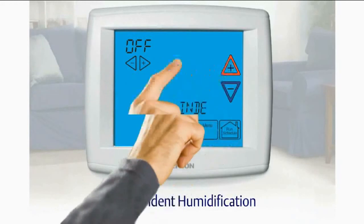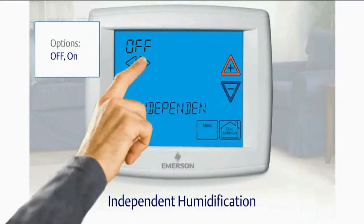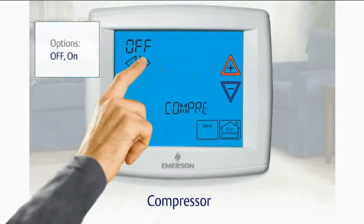Menu item 14, independent humidification. When on is selected, the HM2 output operates when humidity levels are below the desired humidification setting. Menu item 15 is compressor lockout. When on is selected, you have a 5-minute time delay between compressor cycles.